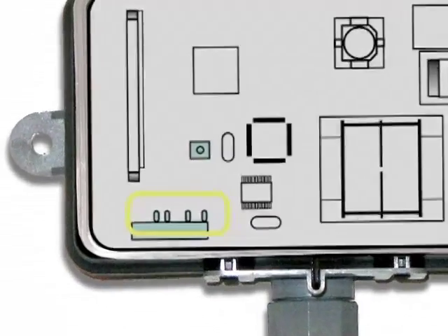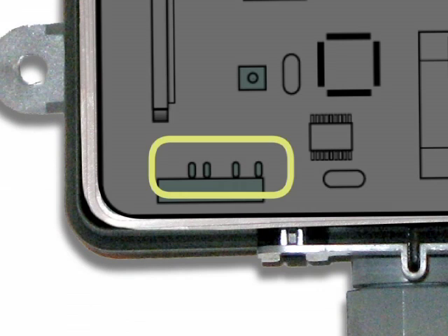After you have installed and tested the switch, the LEDs provide an indicator of paging coverage. If none of the LEDs are on, it means that the switch is not receiving any paging and most likely indicates that it is out of range of paging coverage. Refer to your supervisor on the next steps to take. If there is a green LED that is continuously blinking on for about 2 seconds and off for 2 seconds, it is an indication that the switch is hearing paging on the appropriate frequency and indicates that the unit has paging coverage. If the green LED is on continuously, it means the switch has received a paging command.